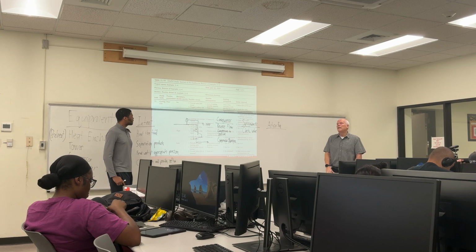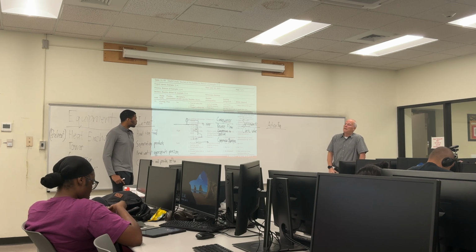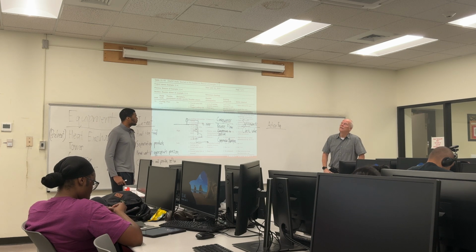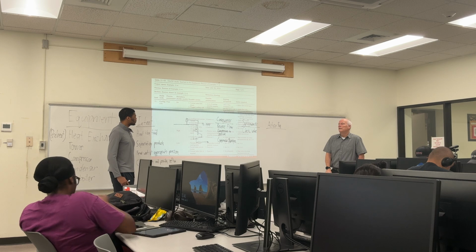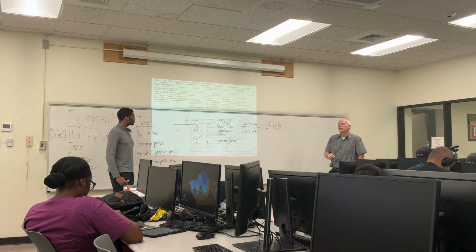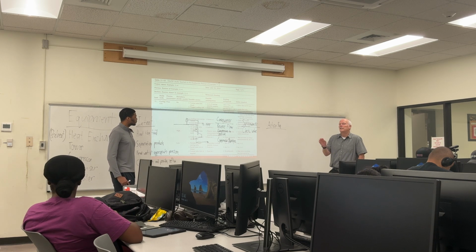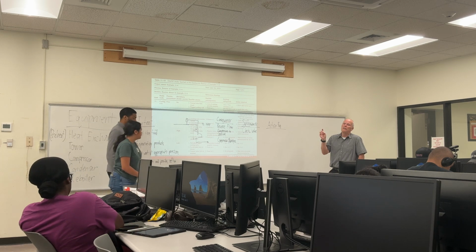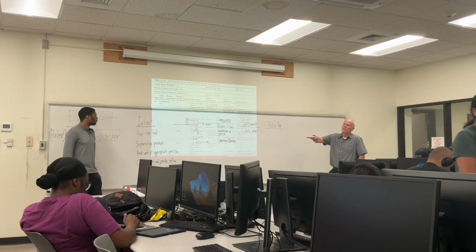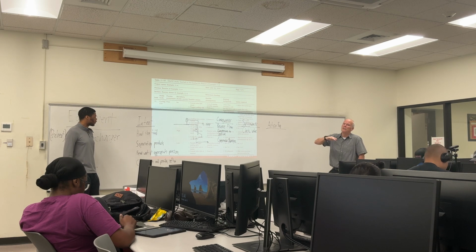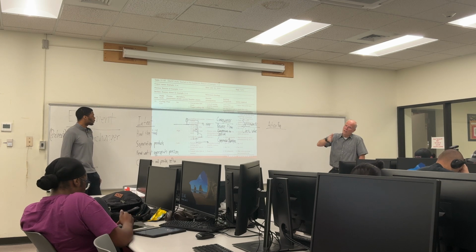Normally, if a big piece of rotating equipment shuts down, then that PLC will tell you why it shut down. Those are called first outs. Because a lot of times when big equipment shuts down, you've got this safety instrument system logic that starts shutting things down.